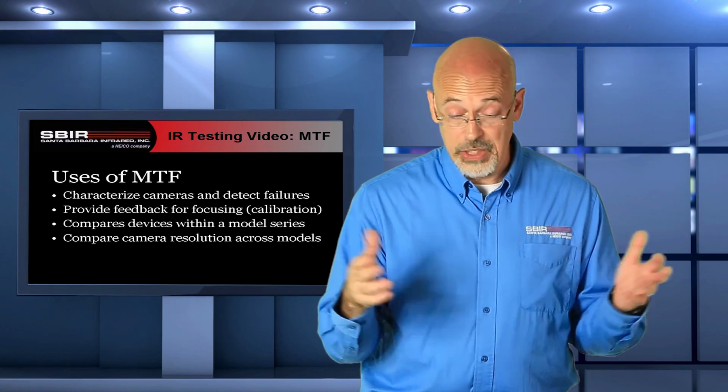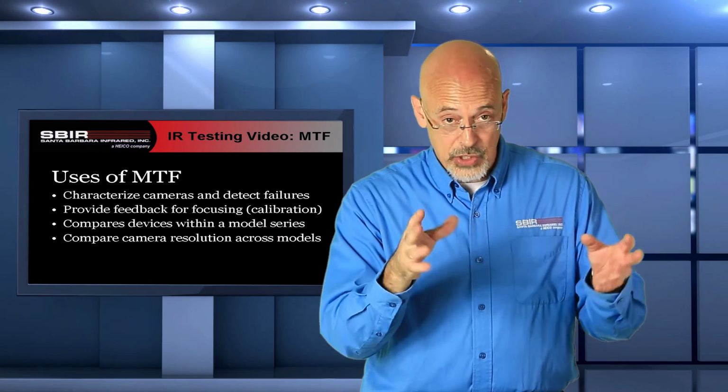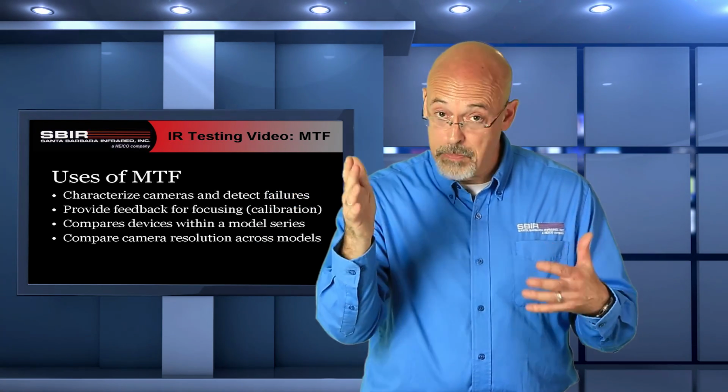We can look at an MTF, we can actually see an MTF occurring live, and as we adjust the focus, see it change, and we try to peak or get the best MTF we can out of the system, and that's our optimal focus. We can compare devices within a model series with that MTF to make sure we're manufacturing it properly. We can compare across cameras. We have to be a little bit careful about what we're looking at, and to also remember that even though something may have a higher or a lower MTF at a particular spatial frequency, it all matters on what we're trying to do.